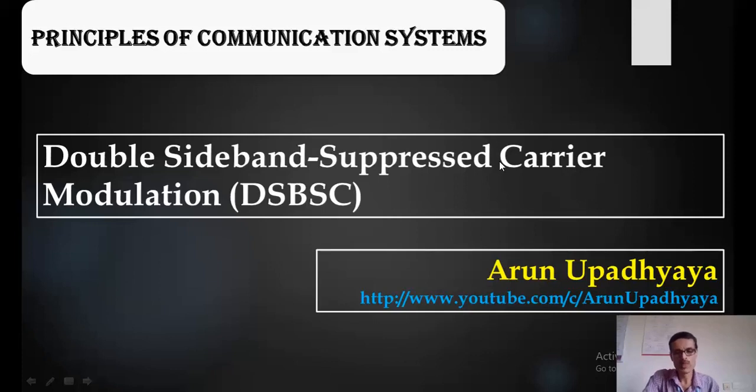Hello everyone. In this video, I will explain a type of amplitude modulation which is called double sideband suppressed carrier modulation. As I told, this is a type of amplitude modulation where we change the amplitude of the carrier signal proportional to the amplitude of the message signal. But before transmitting through the channel, the carrier is suppressed or removed, and only two sidebands, that is the upper sideband and lower sideband, are transmitted to the destination.